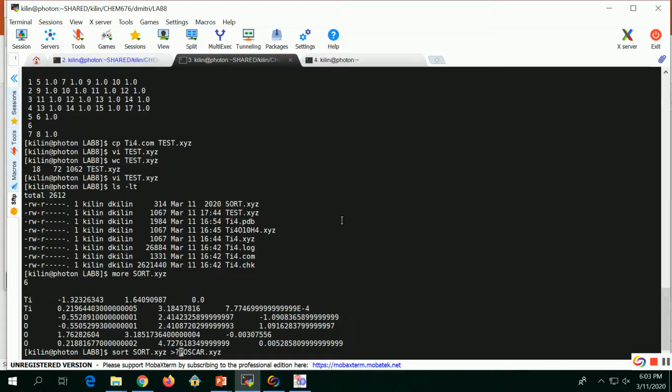So, sorting. There is a little detail, and do not worry, I will repeat it again and again. In the Gaussian GaussView software, we were given names of each element in the model, and it was allowed to list oxygen, then hydrogen, then oxygen, then carbon without any order. VASP software was written by people who like when everything is organized, and they mandate that all atoms are arranged alphabetically.